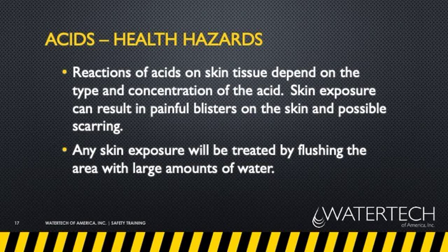Immediately, get to an eye wash or some kind of safety shower. OSHA regulations require our customers who use corrosive chemicals to have a tempered safety shower nearby. The safety shower needs to be located in an area you could find in 10 seconds if you were blindfolded. If you get acid on you, you're most likely going to feel it right away. Get over to that safety shower. Flush with copious amounts of water for 15 minutes. And don't be afraid to seek medical attention.